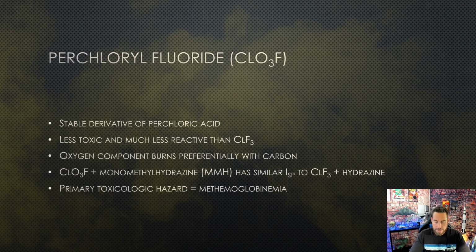So if you look at the hydrocarbons, which we'll talk about, so something like RP1 or rocket propellant 1, it works really well with those because the oxygen that's in perchloryl fluoride reacts really well with the carbon that's in the hydrocarbons. And so when you put those together, it reacts preferentially and it burns really well.